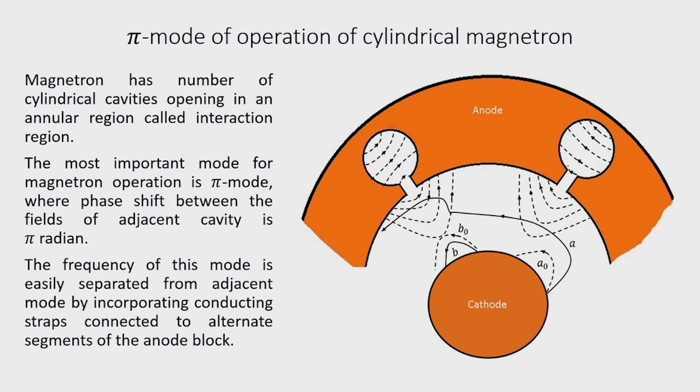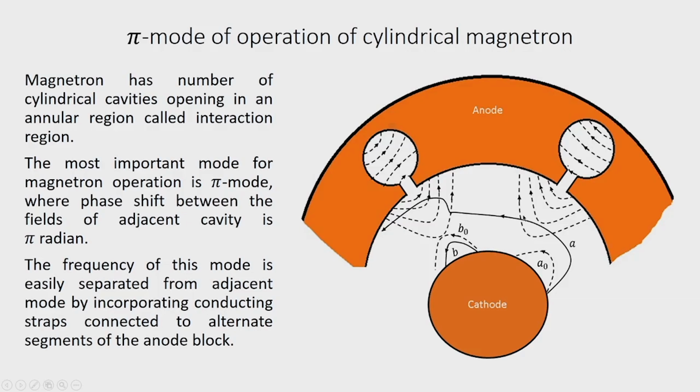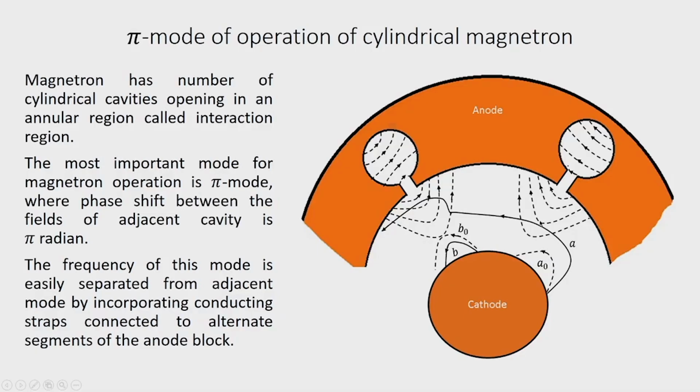Now, in the presence of this RF field, and if the field configuration is favorable, that means here we can see that the electric field component is in the same direction as the velocity of the electron here. So, what will happen here, the electron will get retarded, and as a result its radius will increase, and this electron in the presence of this RF field, instead of following this path, its trajectory will be what is shown as A with larger radius of curvature,